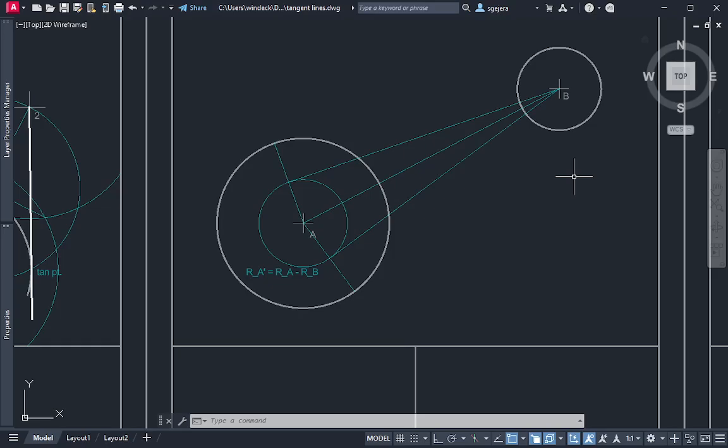Okay? So, the way you find it is, if this was done manually, no? Kukunin nyo yung distance nito and ito. This is diagonal 1. Kukopyahin nyo siya, lipat nyo siya dito, tapos mark kayo ng point dito. Kung saan sila nag-meet, yan yung tangent point at circle B. So, that's how you do it using compass, no? Using your pencil and paper.